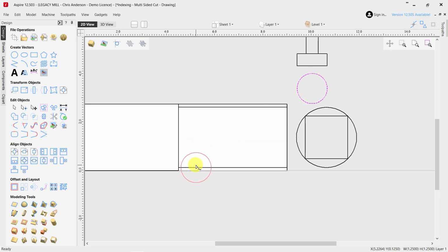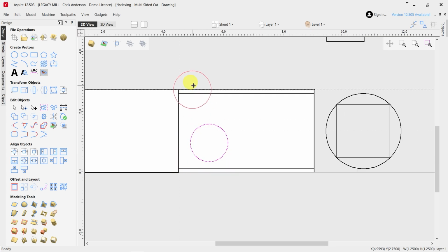If we're looking at the top of the material and this is the surfacing cutter rotating from a top view, the cutter is going to approach right here at a starting point. It's then going to travel down the stock to the ending position, and then it's going to cut across the material and then cut across that edge till it gets to the start position again, and then cut all the way back. Then it's going to simply zigzag back and forth until it works its way all the way to the middle, making sure that we've cleared that entire area and making it flat.